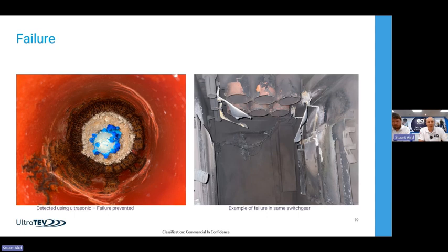So if you're ever going to operate switchgear, or you're ever around them, then make sure you've done a thorough PD survey of your assets. Especially about to rack into an unused cubicle, that side of things. It takes 2 minutes to have a quick check for ultrasonic activity, and could make a big difference.